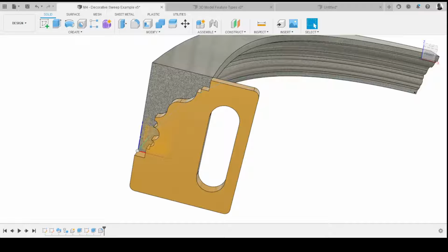I just thought I'd mention that. I'm sure you're all aware you can reuse sketches time and time again. And good practice is not to have loads of sketch, feature, but if you can put things all on one sketch or fewer sketches and drive various features from those fewer sketches, it's always going to make your life easier when you're modeling.